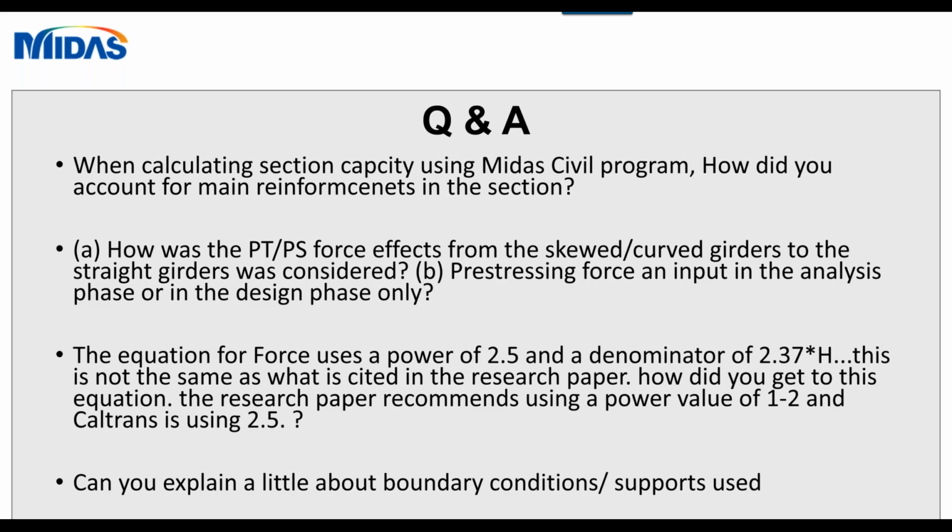So the software has the capabilities to lay the reinforcing for flexure and shear. So I had to go through iterations. First, start with some assumptions about reinforcing until it works. So maybe there is another way to do it, but that's how I did it. So I input the reinforcing. If that didn't work, I had to increase it until I feel comfortable with the design.